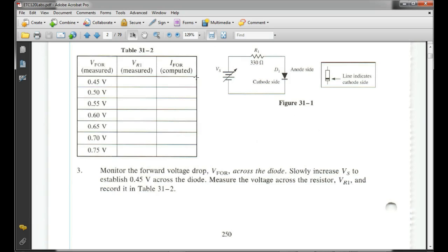How do you measure current? How does an ammeter work? You have to break the circuit and put it in series. So we could do that. We could take the output of our pod and put an ammeter in there all the time, but there's really no big deal, right? You understand that? And you understand you don't have to move your meter lead around. This is what's so neat about this.